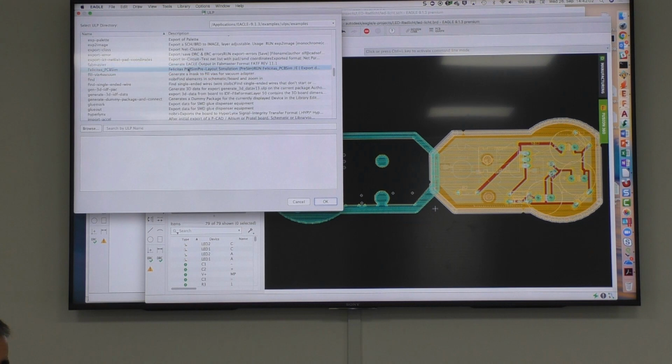That's for example a connection to PCB Sim. That's also a simulation program. It was done some years ago. PCB Sim does analog simulation, digital simulation. It's up to antenna design, all the stuff. The guy who made this ULP, he's the master of the PCB Sim, and he was looking for a schematic entry tool for his simulation, and then he found EAGLE. He came to us that he wants to have the connection with it. If I would have this PCB Sim installed and I would run the user language program, I get context menus in EAGLE from where I can start the simulation in the other tool. So it's really a very tight connection between PCB Sim and EAGLE.